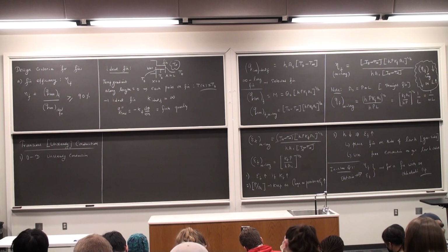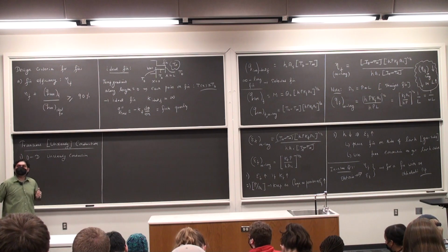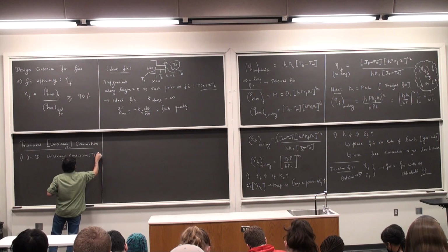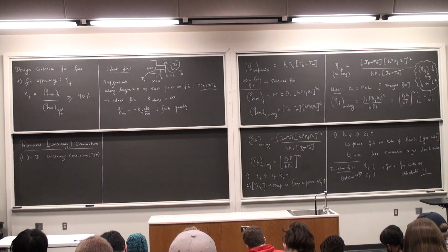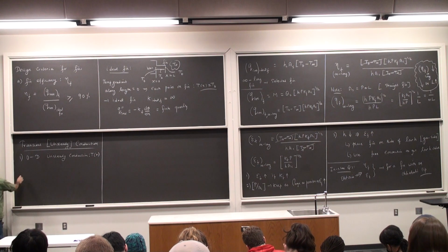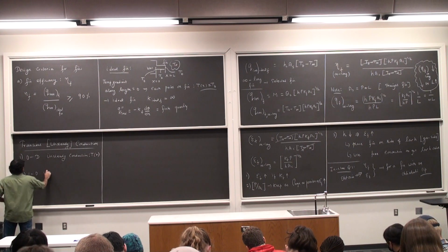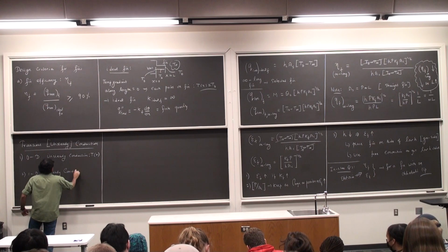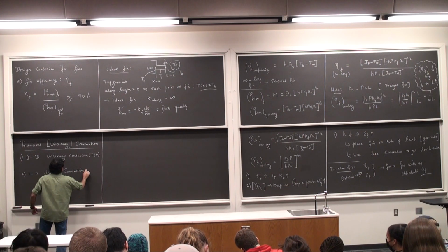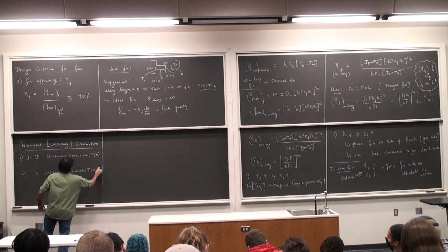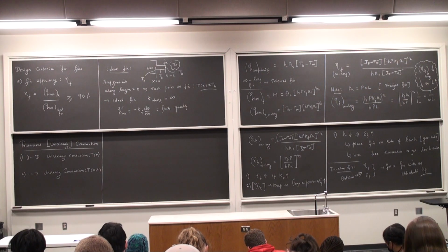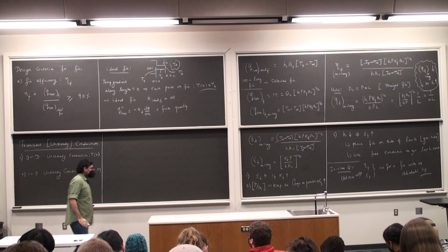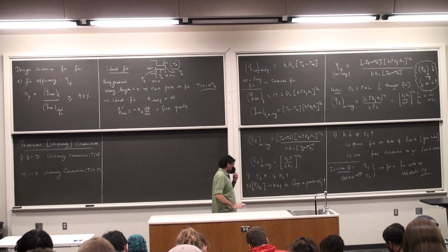Zero dimension means that temperature is just a function of time. And 1D unsteady conduction, where temperature is a function of one of the spatial variables and time. 2D is two spatial variables, 3D is the entire works, which is very difficult to solve.